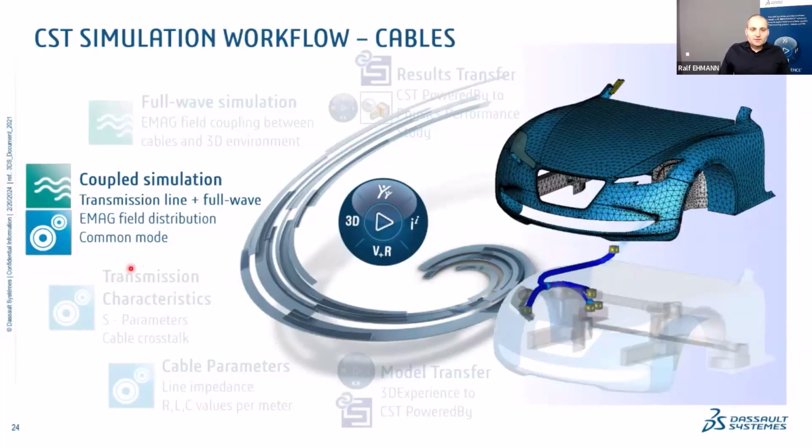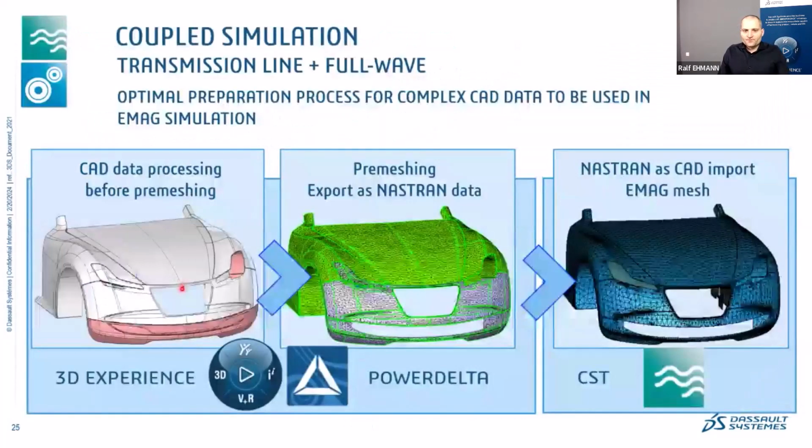And let's start from the situation where we wanted to see exactly how this cable harness interacts with other systems in our model. In this case, it's how much of this interference coming from the PDN can, or can not, upset, for example, our digital audio system. So of course, in order to do that, we need to have not only the cable harnesses, but also the CAD data imported. But you saw that already that it's done.